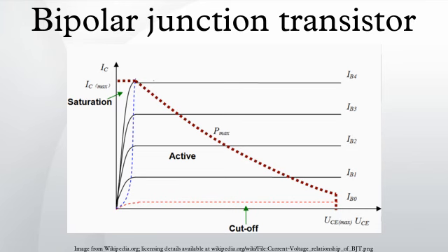Voltage, current, and charge control. The collector-emitter current can be viewed as being controlled by the base-emitter current, or by the base-emitter voltage. These views are related by the current-voltage relation of the base-emitter junction, which is just the usual exponential current-voltage curve of a p-n junction. The physical explanation for collector current is the amount of minority carriers in the base region.